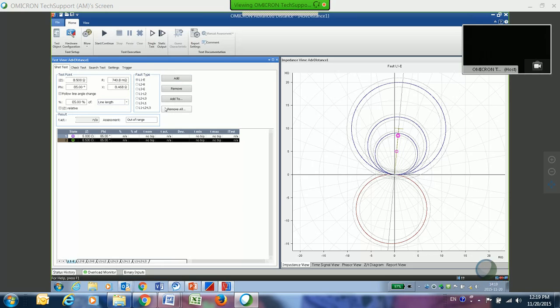And then I can come in and select, the other thing too is I can select what kind of fault type I want. So if I wanted a fault type of line 1 to ground, line 2 to ground, or line 3 to ground, or line to line, or phase to phase values, so it's either A to B or L1 to L2. It just depends on how you have your setup here. Or you can actually do a 3-phase fault here, and it just depends on which one you want to select. So right now, these first two are set up as line to ground faults.